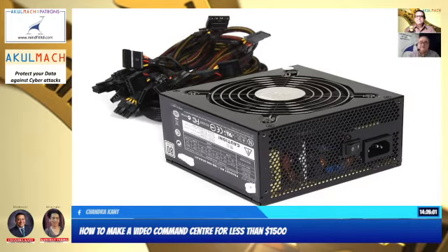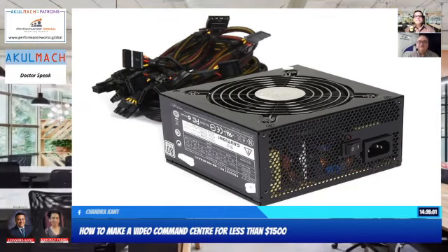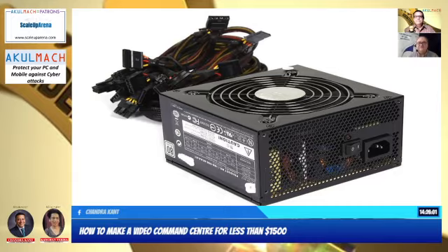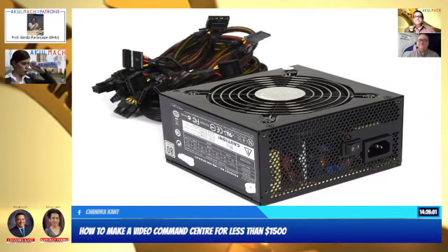They'll work up to the full power, and that fan will kick in and it will be working its guts out. But you never really want to get there. You only really want to get to about 70 to 80% of the limit of the power supply. And that's why, as CK recommends, take it up just one level. It's a few dollars extra, but it's a smart move.